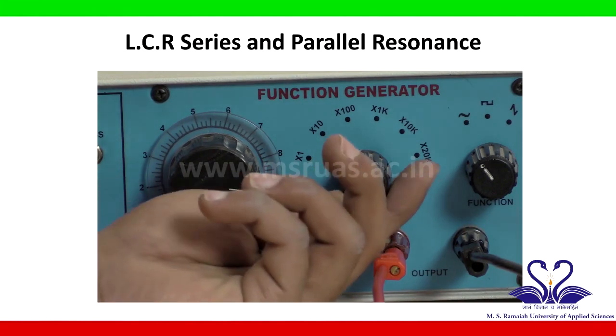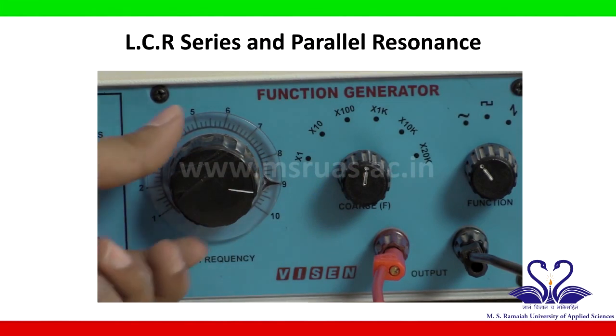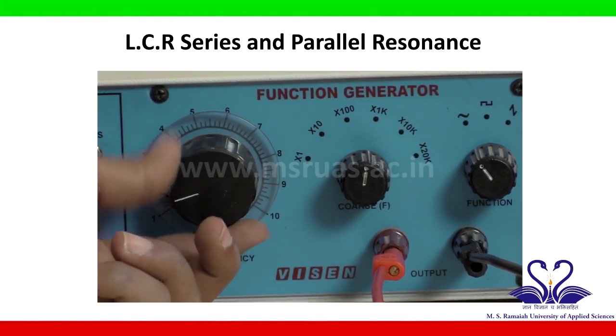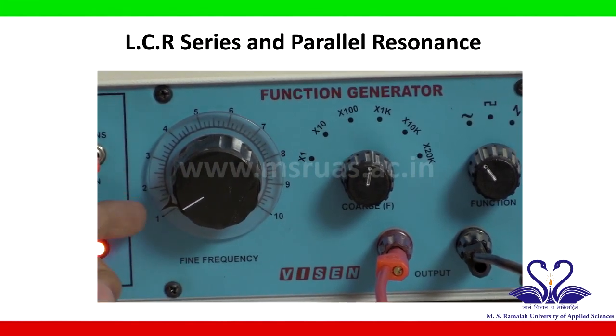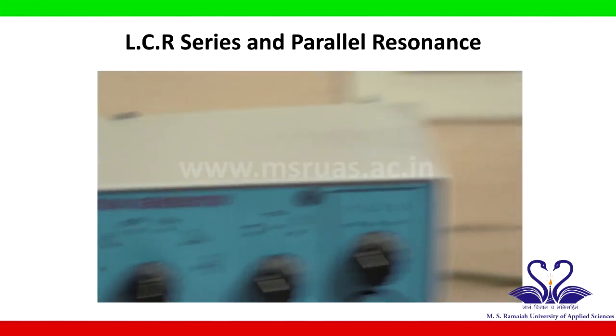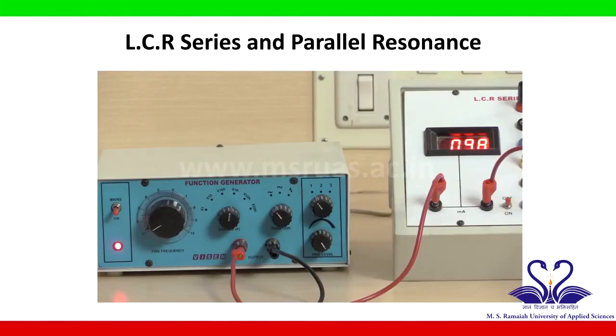Now turn the coarse knob to the 1K position and bring back the fine knob to the 1 position, that is 1 into 1K, which is 1 kilohertz, and note down the corresponding current readings. Now turn the fine knob to 1.5 position, that is between 1 and 2, that is 1.5 kilohertz.